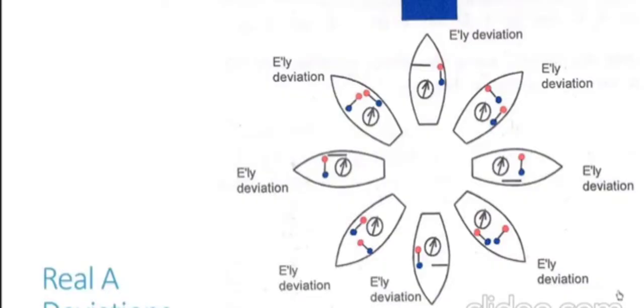This is the induced magnetism of the horizontal soft iron structures by the Earth's magnetism. Let's now see, at different headings, what deviation is generated because of this induced magnetism. As you can see in the diagram, at every heading it is an easterly deviation. You see north heading, northeast, easterly, southeasterly, southerly. On all the headings, they are denoting that the vessel has an easterly deviation.